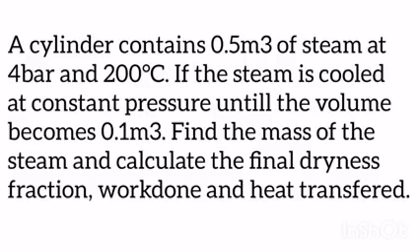Okay, so let's consider the question. A cylinder contains 0.5 meter cube of steam at 4 bar and 200 degrees Celsius. If the steam is cooled at constant pressure until the volume becomes 0.1 meter cube. Question says find the mass of the steam and calculate the final dryness fraction, work done, and heat transferred.